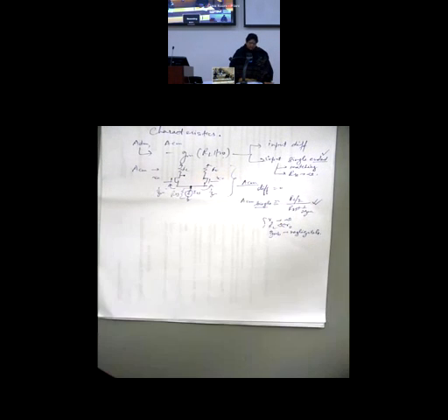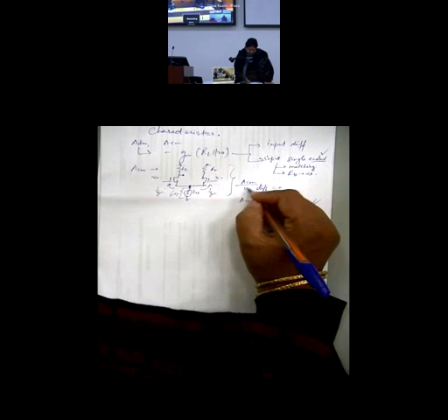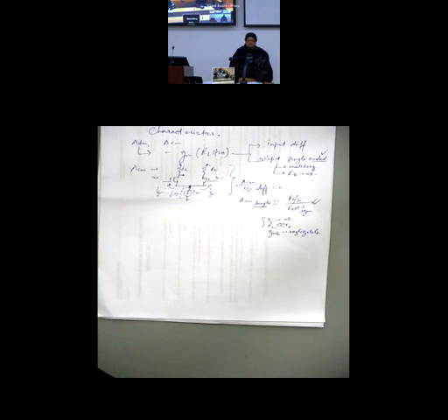This will be ACM, and remember this is only when you are tapping single-ended output. Because if your output is differential, your net output will be 0. But if you tap it single-endedly, because we are not taking any difference now, in that case, you will have an ACM.